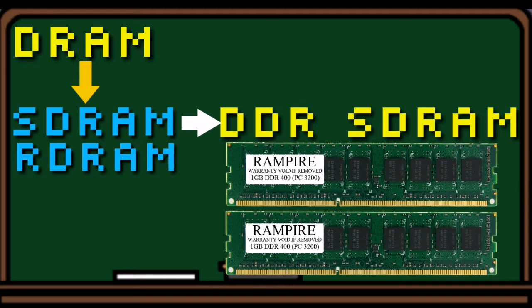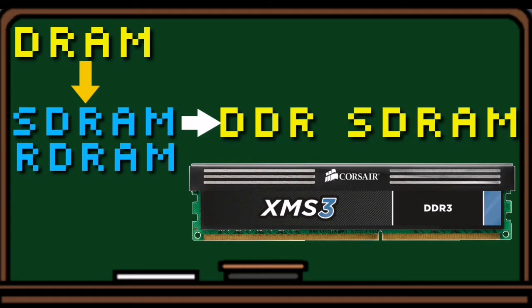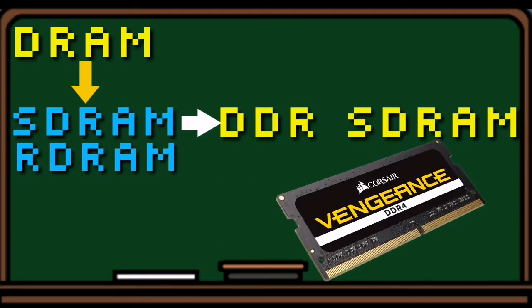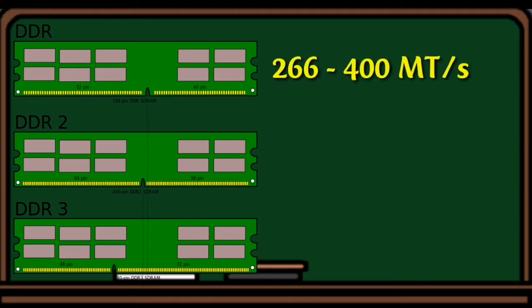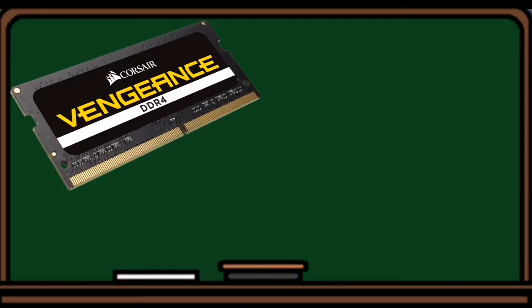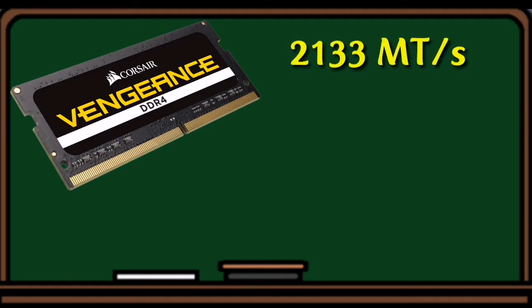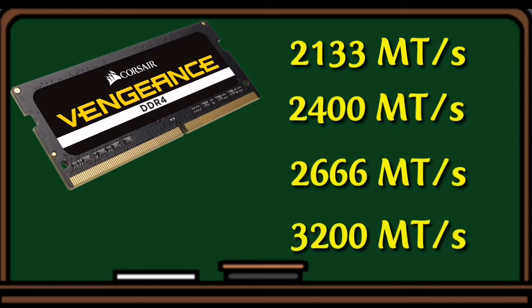DDR1 SDRAM has been succeeded by DDR2, DDR3, and most recently, DDR4 SDRAM. Although operating on the same principles, the modules are not backward compatible. Each generation delivers higher transfer rates and faster performance. The latest DDR4 modules, for example, feature fast transfer rates at 2133, 2400, 2666, and even 3200 mega transfers per second.